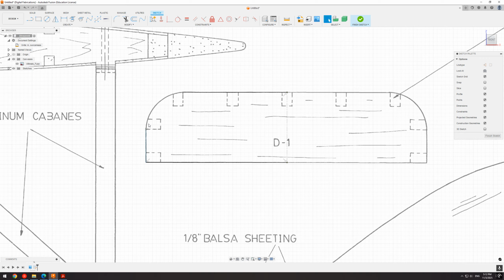Okay, so now we're at the, you could say it's the most difficult part, but it's actually quite easy with the method I'm about to show you. What we need here is what's called a spline, which is a squiggly line in CAD terms. A lot of folks go immediately for the fit point spline, but I actually like the control point spline. And you can find these, since I use them a lot, I have them in the toolbar permanently. But you can actually come down here in the create menu and hit spline, and we're going to do control point spline. Okay?